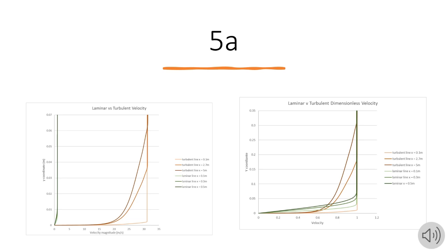In the graph on the left, we can see that the turbulent flow reaches free stream at a far greater distance from the plate when compared to the laminar flow case. This is caused by the friction at the plate surface. The greater the velocity, the greater the shear force applied to the wall. Since the turbulent case has fluid that is 30 times faster, this causes greater friction forces between the fluid layers and therefore a larger boundary layer.